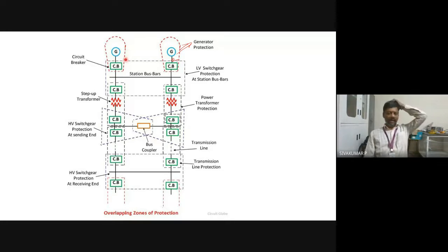For such high megawatt ratings, to reduce the current carrying conductor size, we introduce 400 kV. So the 400 kV transformer steps up from 11 kV to 400 kV, and the power is then transmitted by the transmission line. This is the step up transformer. This transformer is also called a power transformer.